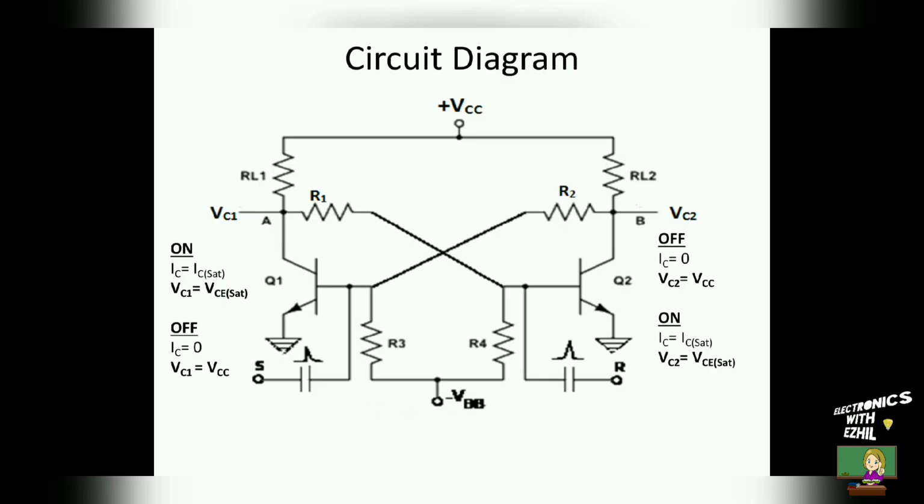When the power supply is switched on, both the transistors Q1 and Q2 are trying to conduct. Although the components present in both the stages are identical, one of the transistors will conduct more than the other due to the difference in the doping levels of transistors 1 and 2. Now let us assume that transistor 1 is conducting more than transistor 2 for our discussion.